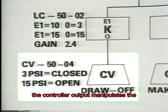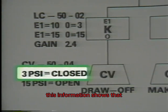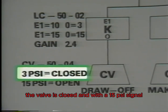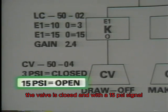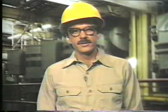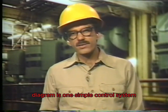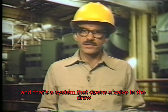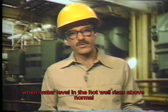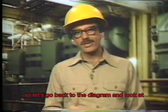The controller output manipulates the valve in the draw-off line. This information shows that with a 3 psi signal from the controller, the valve is closed, and with a 15 psi signal, the valve is open. Essentially, what we've looked at so far in the control logic diagram is one simple control system, and that's a system that opens a valve in the draw-off line when water level in the hot well rises above normal. But that's not the whole system. So let's go back to the diagram and look at the other half of the system.